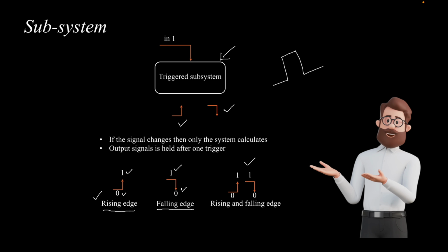So at that moment also you are calculating the signal. Suppose one case could be like you have counted up to 2, right? 0, 1 and 2. So how did this happen? First the rising edge will be calculated, the transition from 0 to 1 in this case. Whenever the falling edge happens, one more count happens. In that case, you will have 1 to 2. So that is how you are getting this 2.